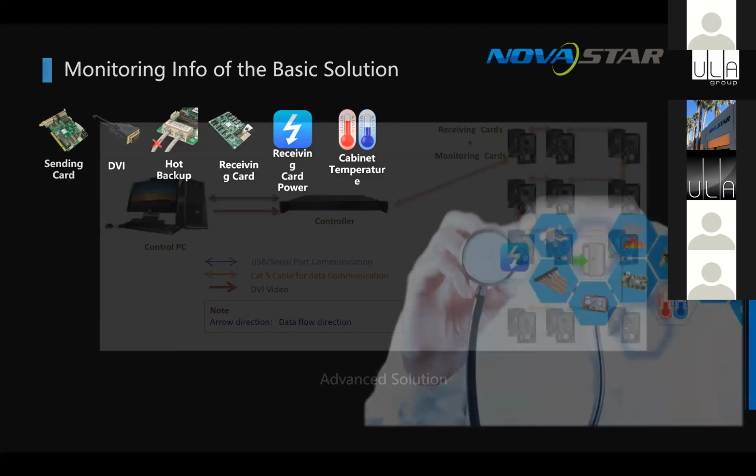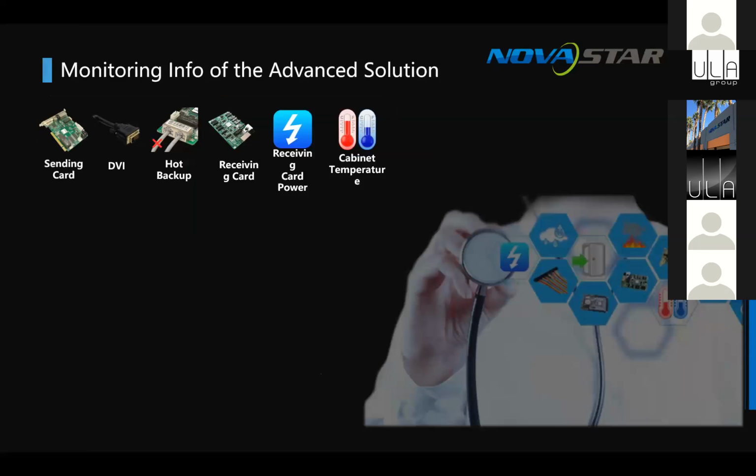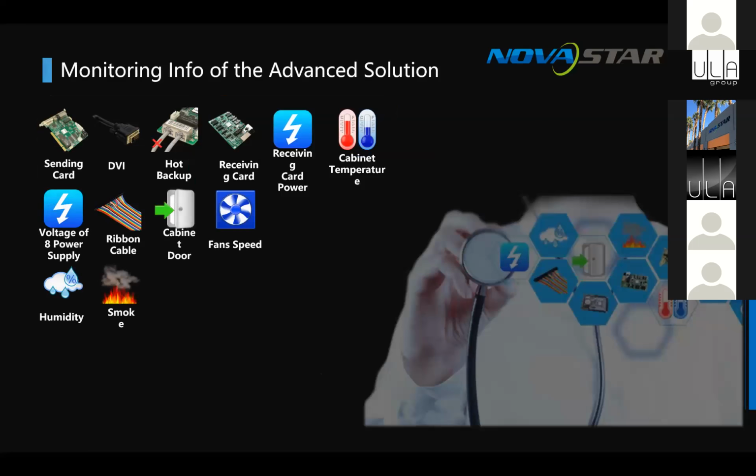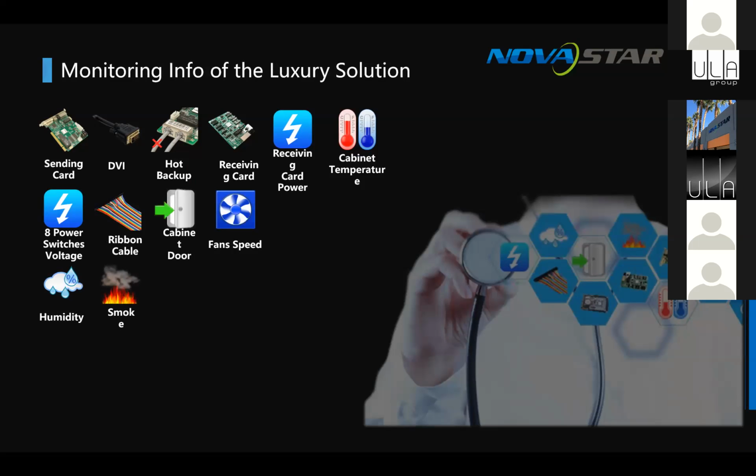And then the next step up is if you get a monitoring card added to that panel. So there is a monitoring card. It's mainly at the bigger cabinets because once again, it's taking up more space, and this is more a fixed installation thing. Some of the features that this will give you, in addition, depending once again how it's configured, it'll do extra things like tell if you've got a faulty ribbon cable, the door's open, all the stuff that's mentioned there. So there's definitely some extra features there.